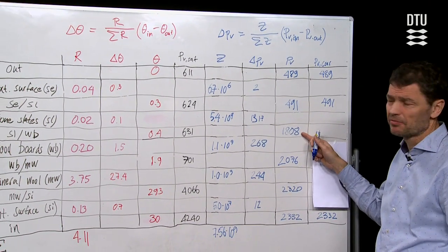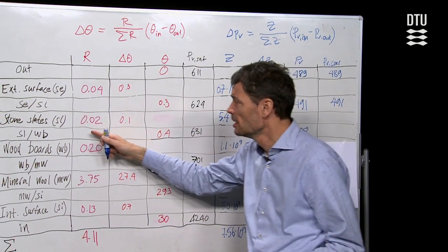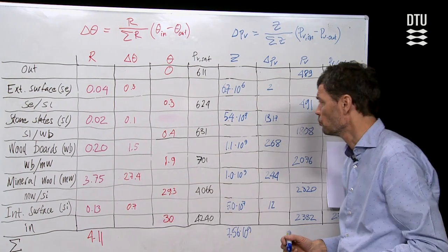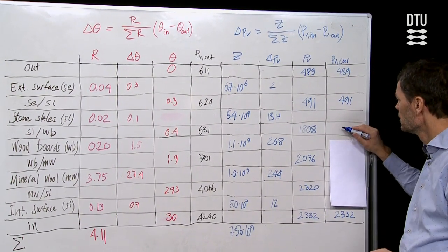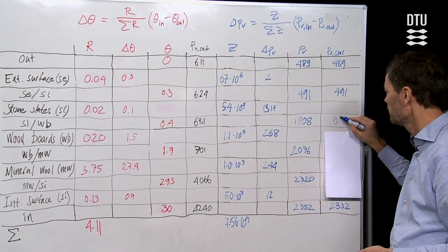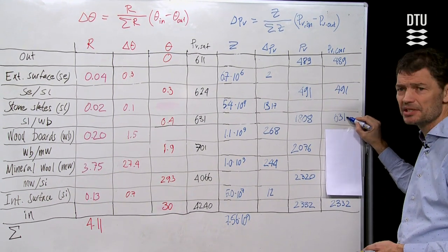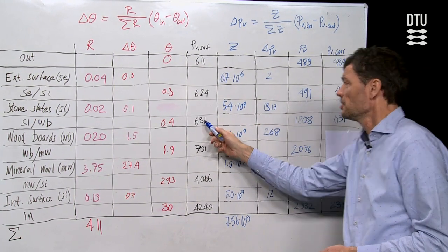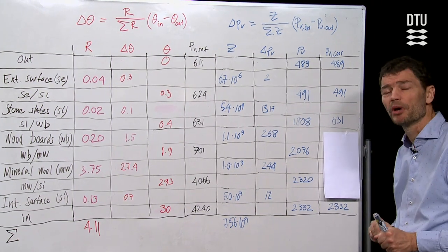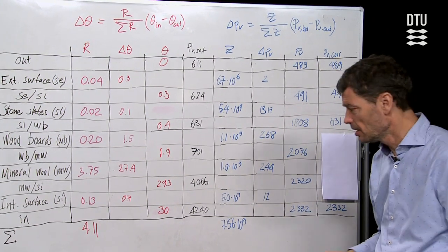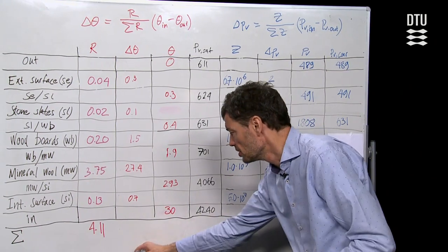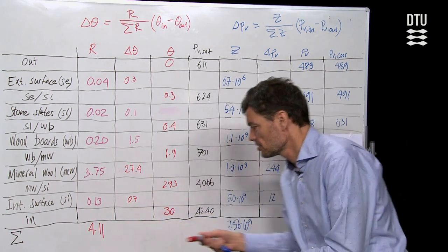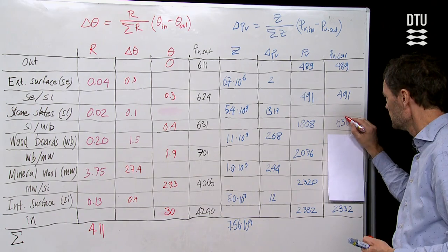So it seems that we have condensation that would take place just on the interior surface of the slates, or on the outside of the wooden boards in our roof construction. When we have condensation, we cannot have a higher vapor pressure than the saturation value. So I put here 631, which is the saturation value I just put over there. Now, to make the correction, I need to distribute the conditions between 631, where I had the condensation taking place. I'll just bring that in here.